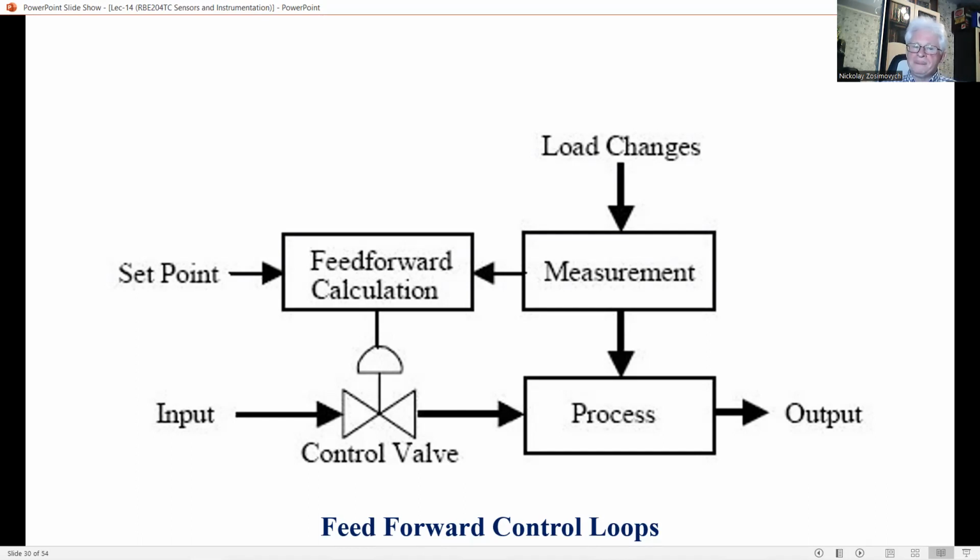Feedback control for control signal determined according to the plant response. Open loop control for plant response not used to determine the control action. Feed-forward control for control signal determined according to the plant excitation or a model of the plant.